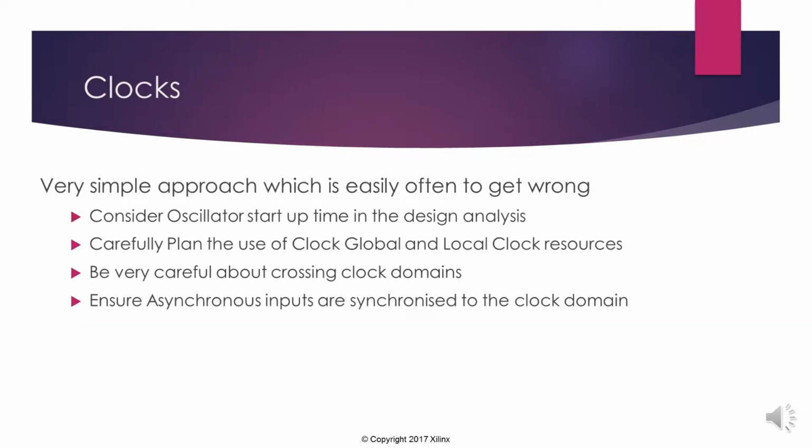Now the next one, it wouldn't surprise you to know, I'm sure, is that there was at least one satellite flying about that had some problems because it had problems with its clocks going into its FPGA, because they'd not considered the oscillator startup time in the design analysis. So we need to plan this very carefully, use the global clocks and the local clock resources carefully, and be very careful about ensuring that if you're crossing a clock domain, we cross it properly and safely and do sufficient analysis on it to prove that it's safe to do it.